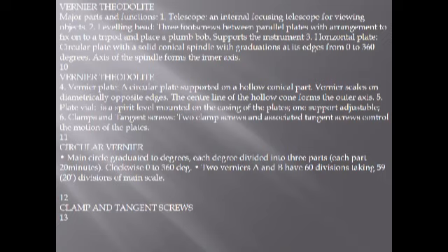And next is the circular main circle graduated, with the circular vernier. The main circle is graduated in degrees, each degree divided into 3 parts, running clockwise from 0 to 360 degrees. There are 2 verniers, with 60 divisions taking 59 divisions. This circular vernier is used for checking the angle, which is given in degrees, minutes and seconds also. These are fixed in the upper part of the theodolite.